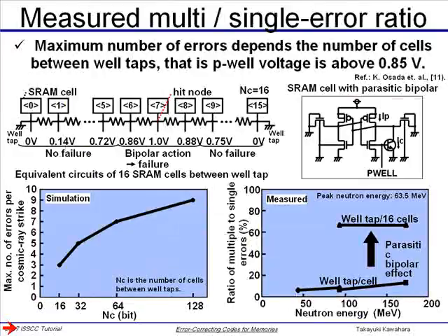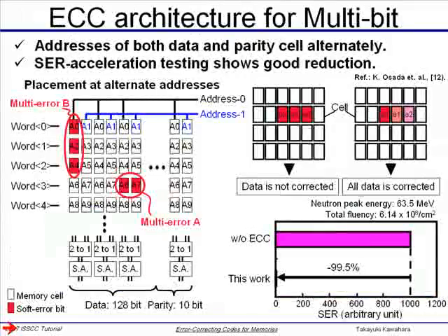This example shows only how the series resistance situation arises. The SRAM cell has a very large resistance in series, and that causes very serious soft errors, and the measured data shows a high possibility of soft errors. Here is the figure I want to explain.